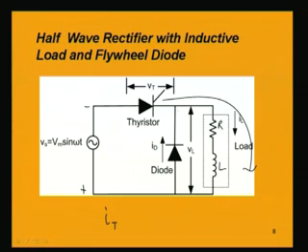But mind it, current flows, but that current will be now bypassed by this diode in this circuit consisting of load and the diode. And the supply will not be allowing any current. That means we do not get the supply current through the thyristor, but we are having a current in the load due to the diode current.